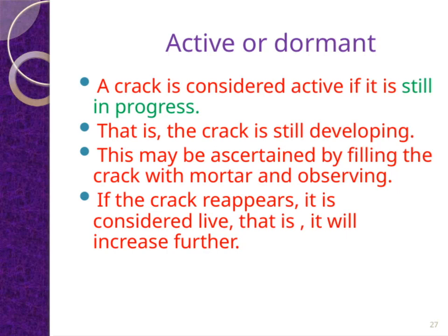A crack is considered active if it is still in progress. That is, if the crack is still developing or growing. To determine this, we can fill the crack with mortar and then observe what happens over time. If the crack reappears after filling, it indicates that the crack is still live or active, meaning it will likely increase further. So, understanding whether a crack is active or dormant is crucial for assessing structural integrity.